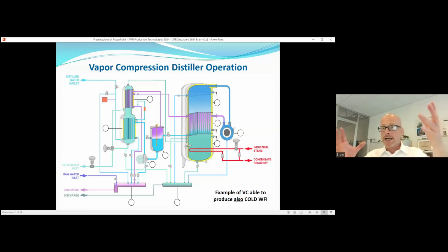For the second physical effect, after the gravity separation, we have the compressing of a gas. You know that when compressing a gas, the resistance between the molecules increases, and you also increase the temperature. So we can reach a higher temperature inside the compressor, depending on the speed of the compressor, the manufacturer, and the capacity of the machine. The temperature can vary a little bit, but this is the job of the compressor.